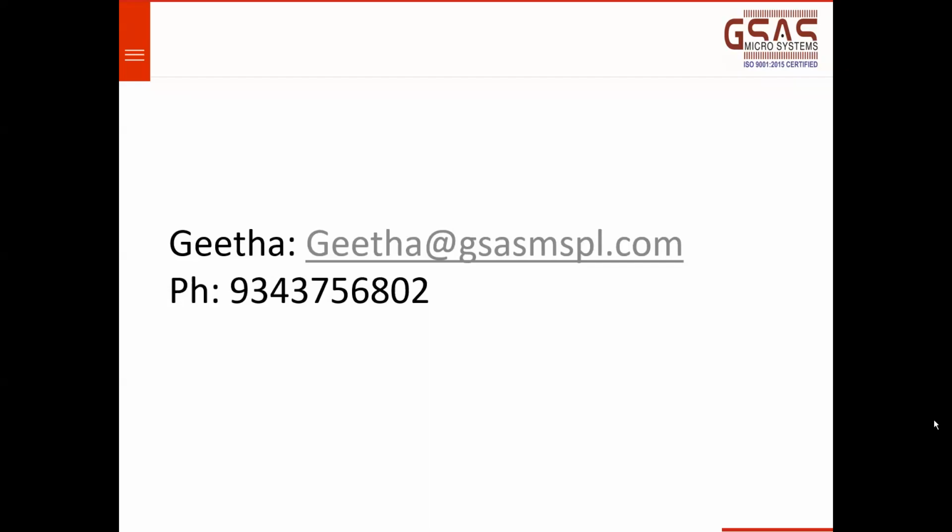I'm sorry, I think I missed your answer. The simulator features available in Keil MicroVision onwards. No, Christina, the simulation feature is available in all the versions, in all the editions of Keil, from the light version to the professional version, including Essential Plus. So one thing I want to tell here is, even if you don't have a license also, you can simulate your peripherals. But yes, it is limited by the code size limitation of 32 KB.